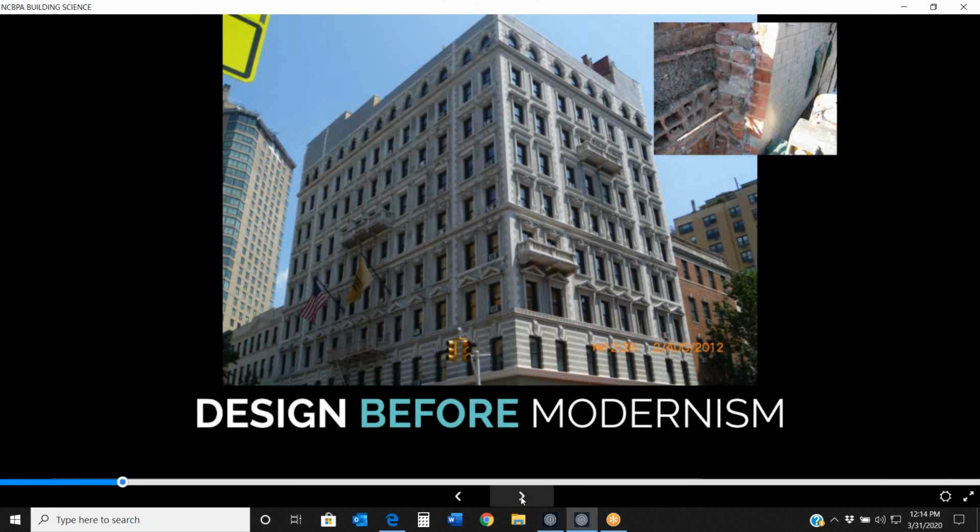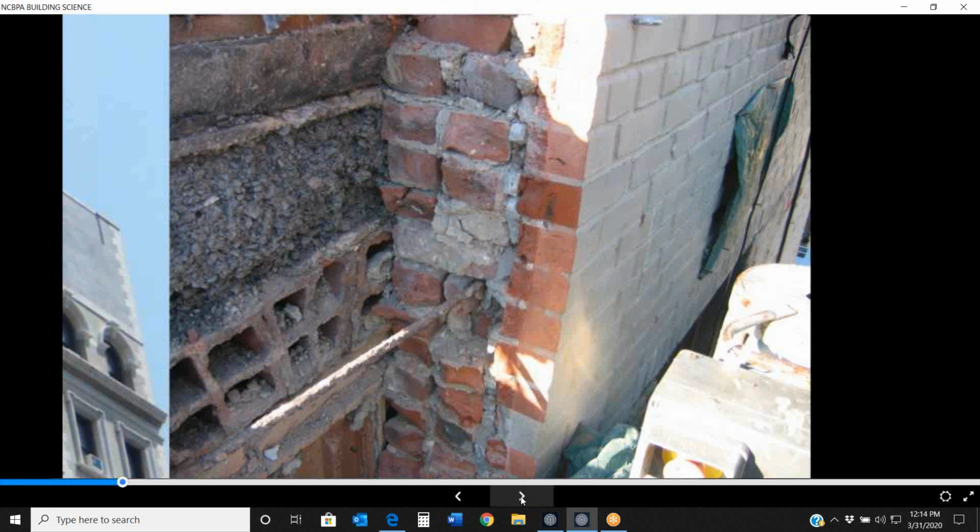Looking at these a little bit closer, it's mostly talking about our materials and how we designed our building. So the first step here is we're building with some really substantial materials that can take the effects of cyclical drying and wetting. As we know, brick can get wet and dry back out, and this was allowed to do this again and again and again over the life of this building without causing a whole lot of issue.